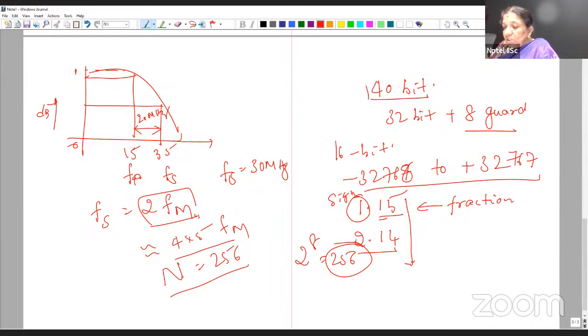That is why most of the time we divide by 2. If it is correctly designed, we can go up to 256 or even 300, but you have to design a stable filter. Even an FIR may become unstable in that case, so usually we try to do 128th order or something like that.